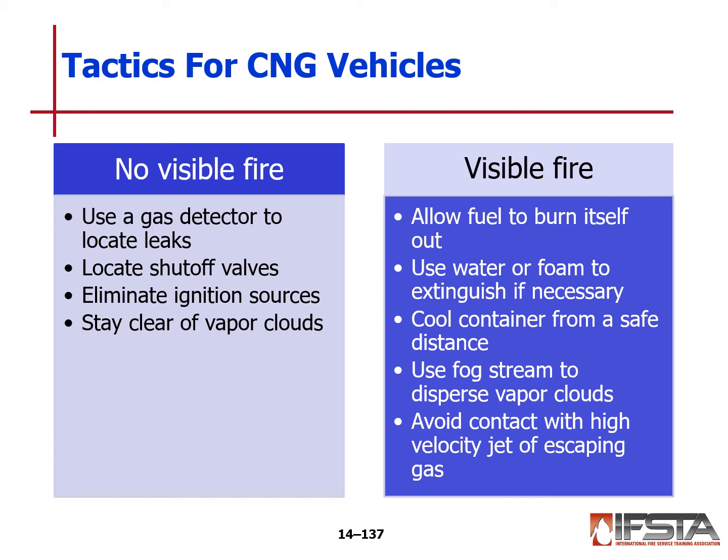With visible fire, allow the fuel to burn itself out. We would use water or foam to extinguish as necessary, cooling the container from safe distances, keeping an explosion from occurring. Use a fog stream to disperse any vapor cloud and avoid contact with high velocity jet or escaping gas.